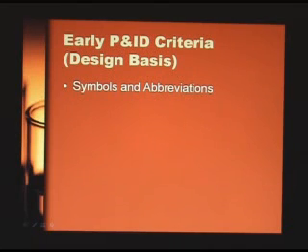Okay. Yes, Oscar? The existing equipment or pipeline? Yeah. If we are connecting new to an existing system, that point is a tie-in point. So the tie-in list is a list of these tie-in points. They are listed by location, size, and process characteristics of the fluid that goes in.